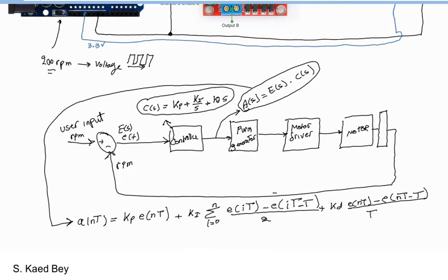So in the open loop configuration that we have already done before, we didn't have any controller involved. All we were doing was simply having the controller replaced by a simple RPM to voltage relation based on the datasheet. And the output of the PWM is always constant, and the motor is being driven at a certain RPM. And we were only displaying the encoder response on the screen. There was no feedback and there was no subtraction at all. So that was the open loop configuration.